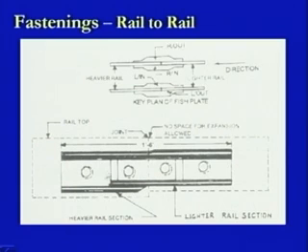So, again we are using 4 bolts. One bolt is going in this fish plate. There is no overlapping area here. Similarly, there is no overlapping area here, and then 2 bolts will be coming through this additional thickness area, and this is how it is being connected.